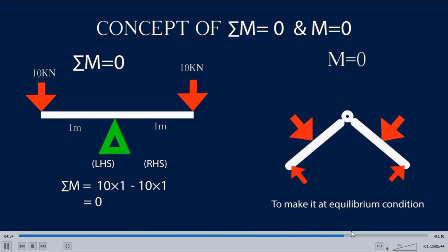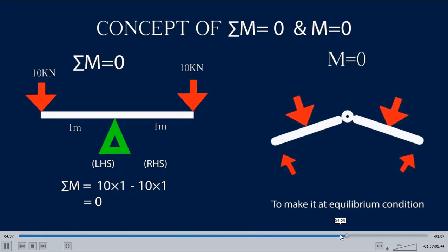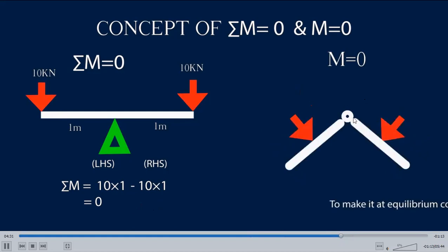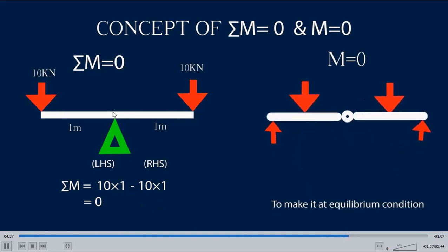If it can rotate simply, it's like a door when you look from the top view. So whatever happens, here the bending moment is 0. Why? It can rotate freely, independently, but here it cannot, because it is continuous. To rotate, this part also should rotate, so there will be a resistance. Here it's not like that. They can individually rotate, so the bending moment is 0.